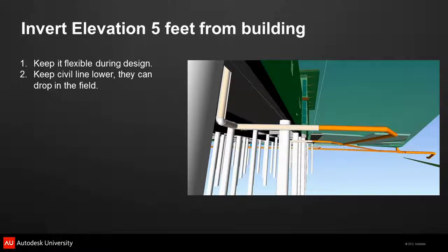So if you've got really long lines, you might start going through the structure, but then you've got to provide room for movement. The civil utilities, it's helpful to at least get them to come up and make sure they're at least lower. And then the plumbing, as it's coming up, you can always dive down and tie into it. You just don't want, obviously, the civil inverts to be higher. So there's a lot of value, if you're getting requests on the design side to provide higher detailed plumbing models, to be sure to ask. We also want that civil model.